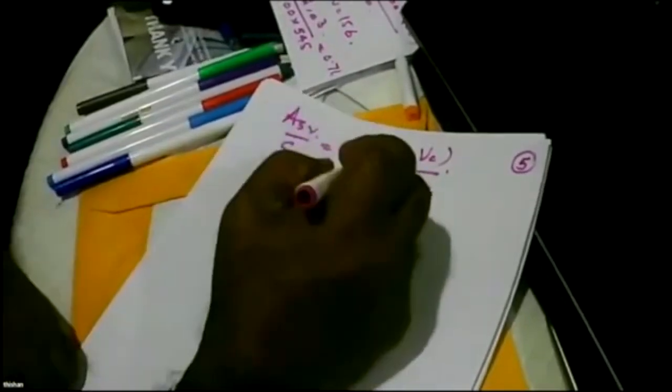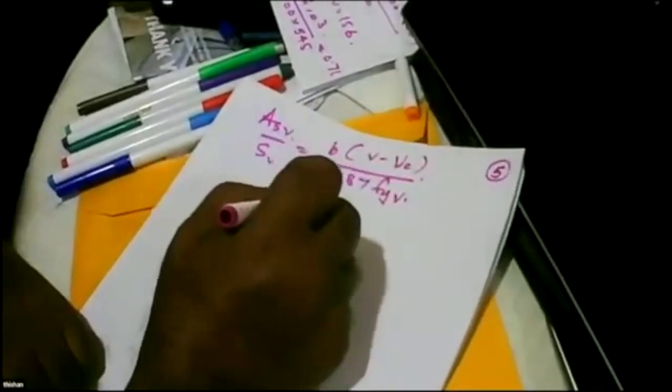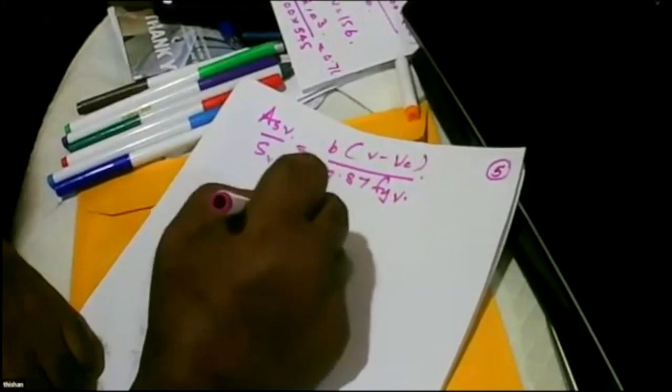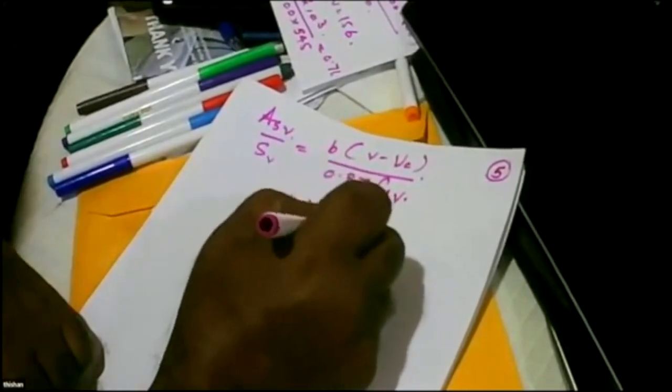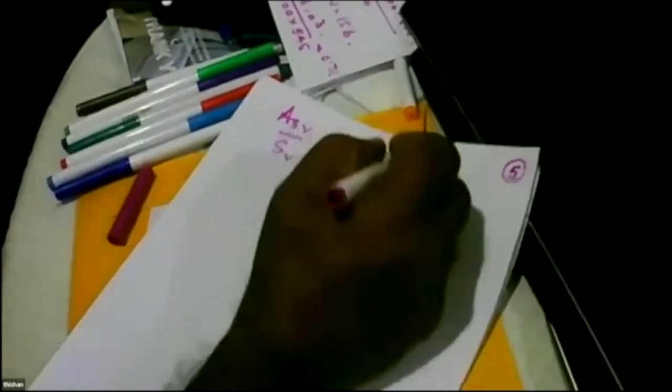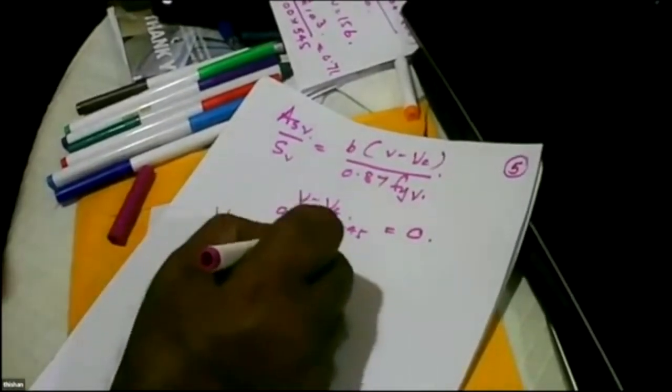Now, what would I do? You can see here we have a term called V minus VC. Now if V is 0.45 and VC is also 0.45, what do you get? 0. Then you get infinity. That is not good. You can't get infinity for the link spacing. So it says V minus VC should be greater than 0.4.